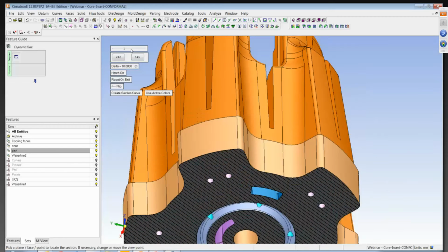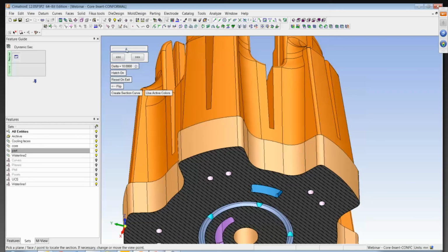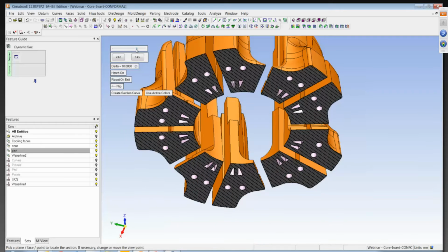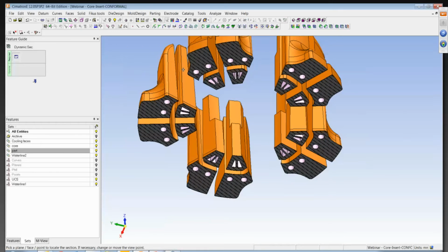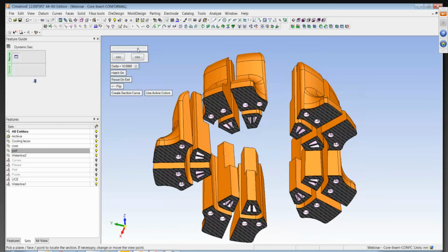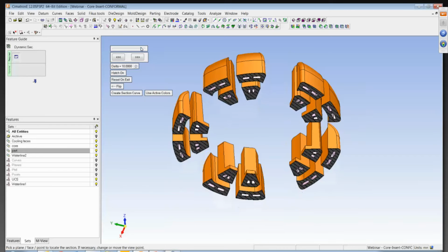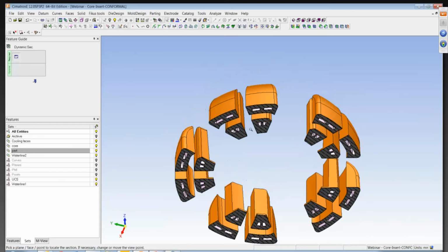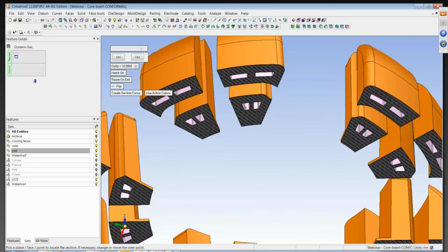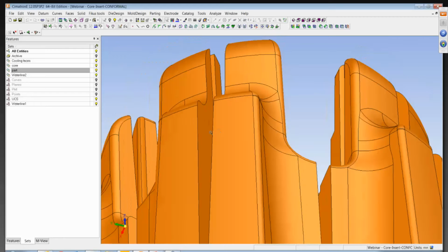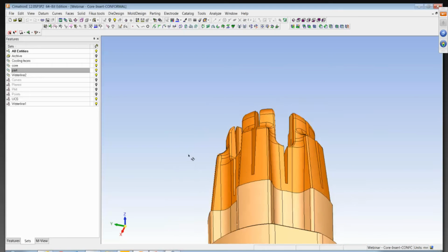As we continue to drag this through, you should see other different shapes appear. Again, the idea is to keep it as equal distant from the outer edge as possible. And there you see it down into the tip, how it's had to completely change its shape. Looking at the cross-section here, there is no way that's the same area as in other places of this water line. Just to point that out to you, and we'll talk about that as we look a little closer at it. Let's look at this from another point of view here.